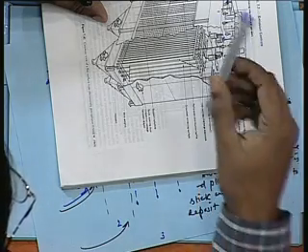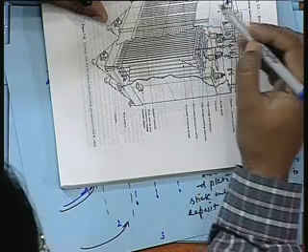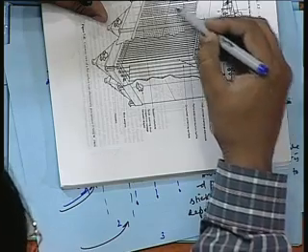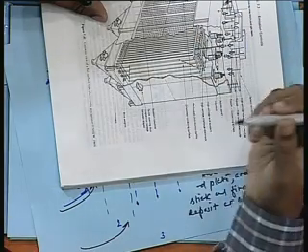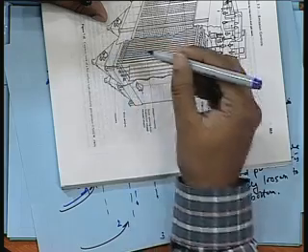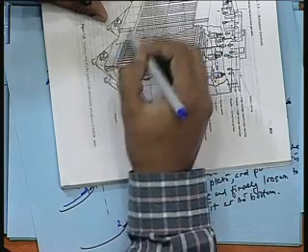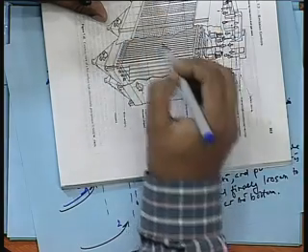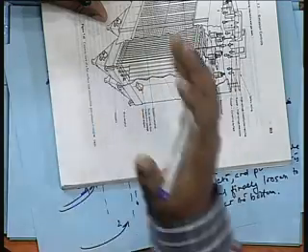Through these outer surfaces the gases would come out, and the particulates would settle at the bottom or remain stuck to the grounded collector plates. This is mostly how it looks. So this is the electrostatic precipitator, which is very common in use nowadays.